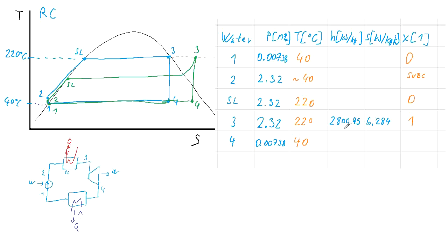Now, from this point and enthalpy at some specified quality with the diagram, or from the thermodynamic functions using the steam quality and the temperature or the pressure, we can get the enthalpy at saturated liquid at the high pressure, which is 943.58 kilojoules per kilogram, and eventually if you want to get entropy it would be 2.517, but here we don't really need that entropy that much.